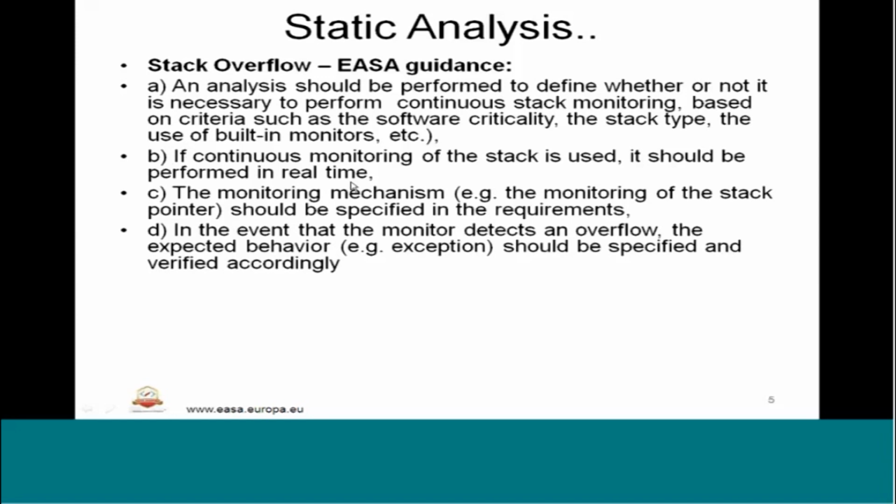The next one: if continuous monitoring of the stack is used, it should be performed in real time. That means if the monitoring part is there within the critical embedded software, then it should be performed during real time. The monitoring mechanism, for example the monitoring of the stack pointer, should be specified in the requirements.